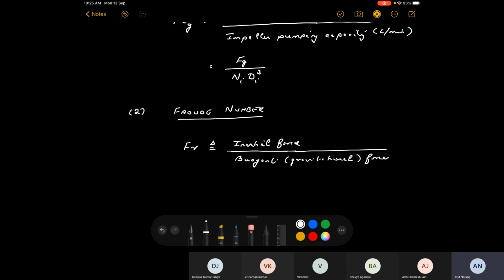So what are we talking about here? Well, momentum can be transferred by various mechanisms. Momentum can be transferred by convection, which is to say bulk flow, where packets of liquid just jump around in big chunks, carrying momentum with them. This is called convective momentum transfer or inertial momentum transfer. When momentum transfer takes place in this fashion, it generates what are called inertial stresses or inertial forces. So these involve bulk motion.